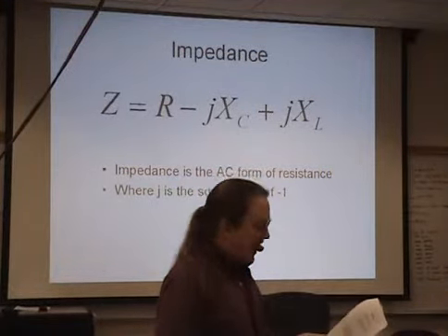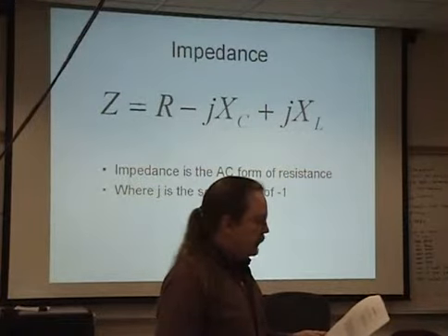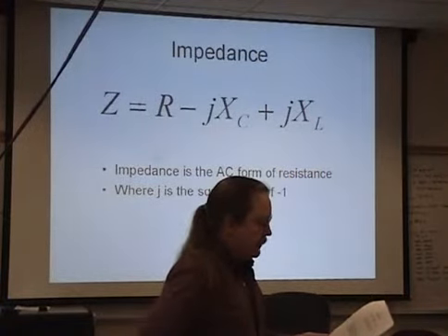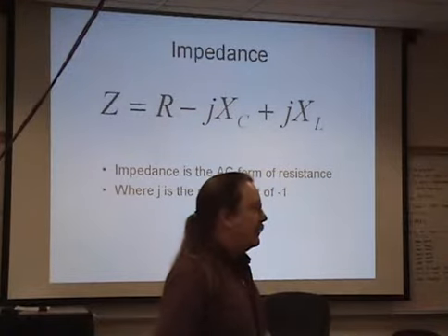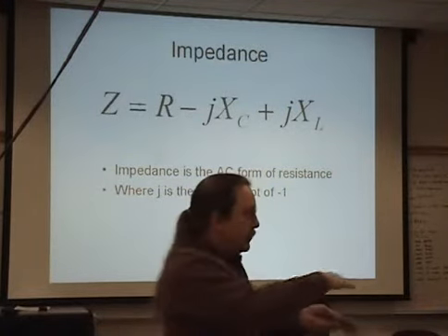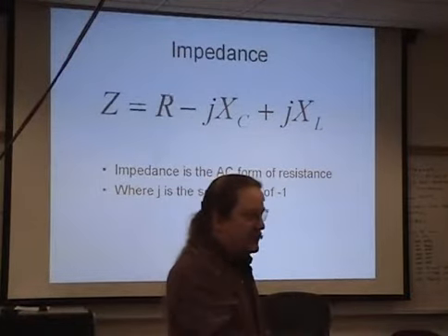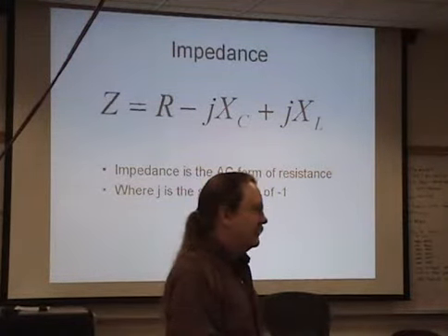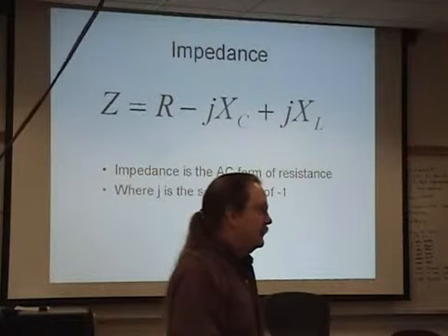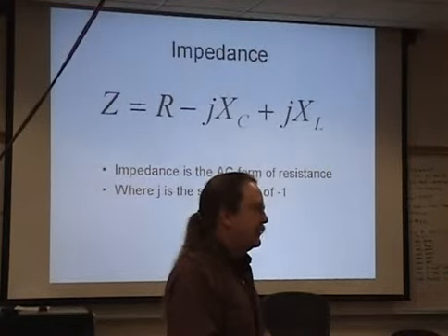Resonance is very important for tuning your radio to get the right frequency, for tuning your antenna tuner to get rid of all of the inductive and capacitive reactance to give a pure resistance to your antenna. It's also good for just plain filtering out all those excess harmonics that come through the system.